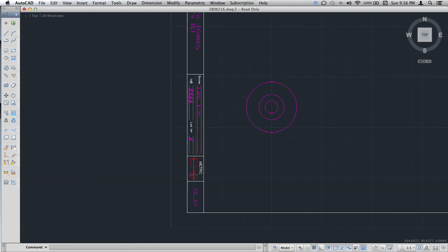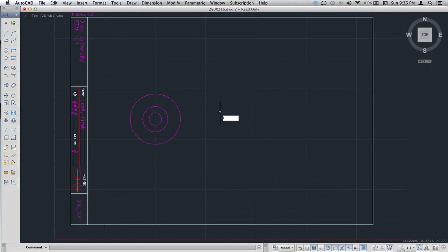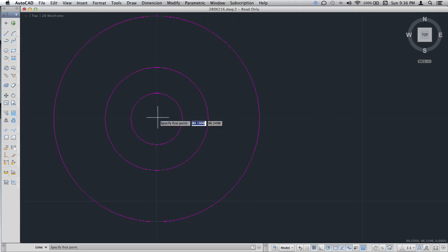Okay. Now what we're going to start doing is really creating some reference lines here. So again, I'm going to start from the center here. So you have to tell it, hey, I want to key off on that center. And how you tell it that you want to key off on the center of this particular circle is just hover over that circle, drag it down nice and calmly till a little green thing appears, specifying that it is in fact the center.